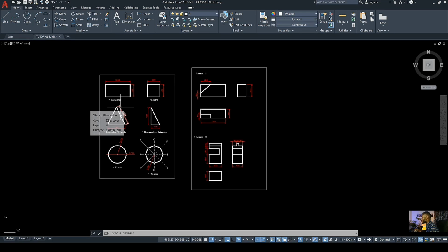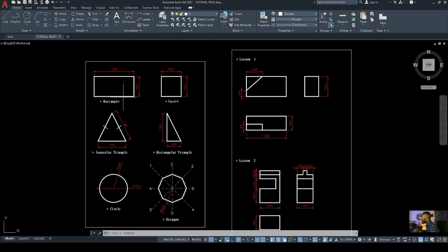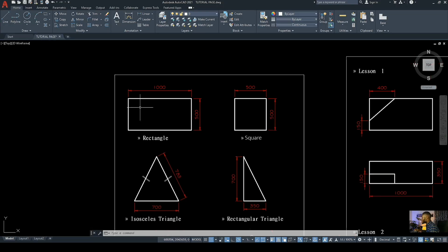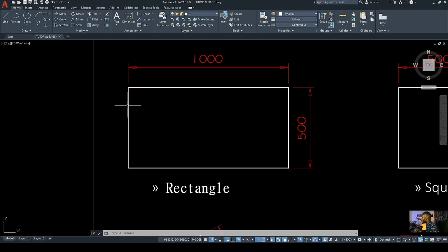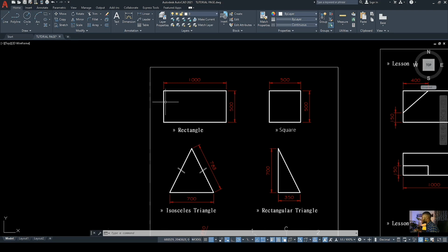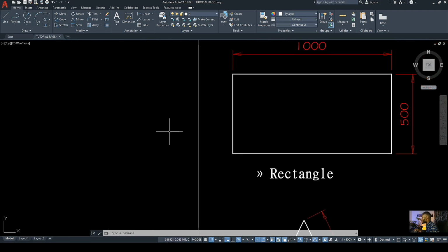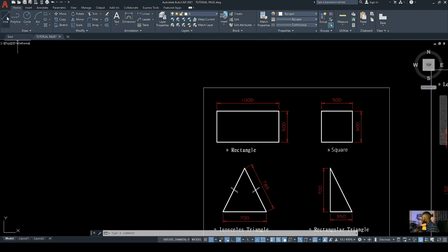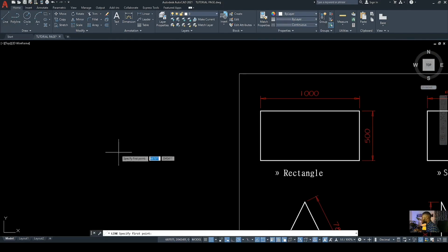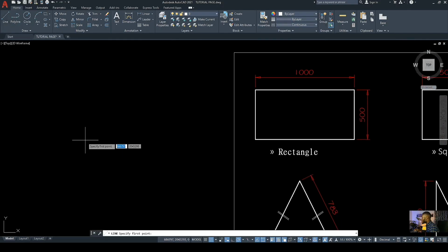On this channel, I'm here to guide you on how to get better at your design skill using AutoCAD and also SketchUp, which is our 3D modeling software. But this video is focused on AutoCAD. So right now, we'll start focusing on each of the examples one by one. Let's start with our right angle. Starting with our right angle, we'll pick our line tool. Once we pick our line tool, we'll draw a baseline, picking a reference point A.